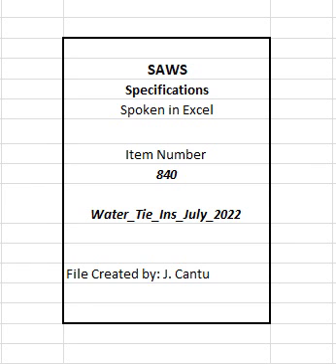11. Contractor to be prepared for water main shutdown as coordinated with SAWS inspector. Fines may be assessed if contractor cancels or delays owner. 12. Contractor to consider dewatering of the main as part of the duration of tie-in work. 13. SAWS cannot guarantee a complete water shutdown. Contractor is responsible for providing adequate dewatering efforts to complete tie-in work.